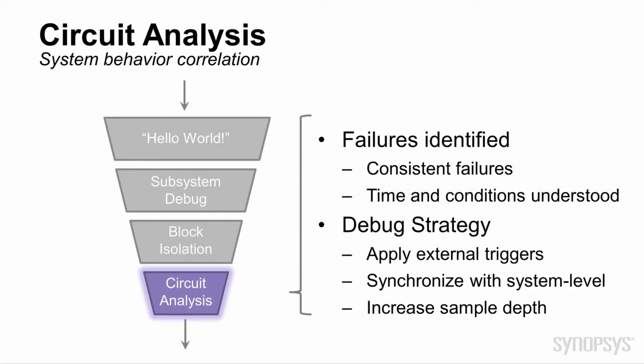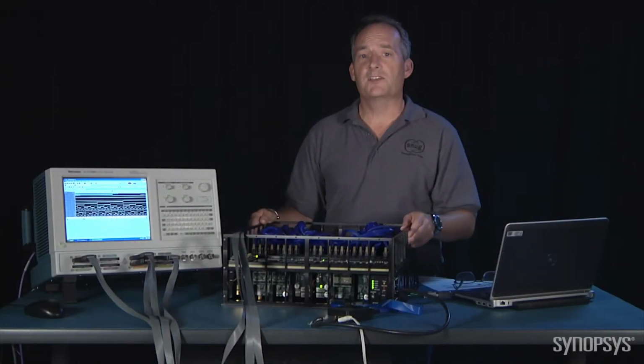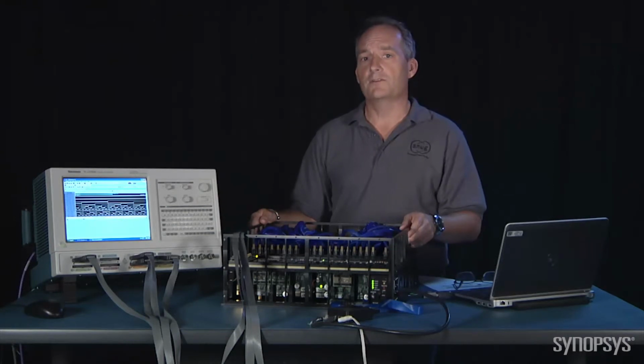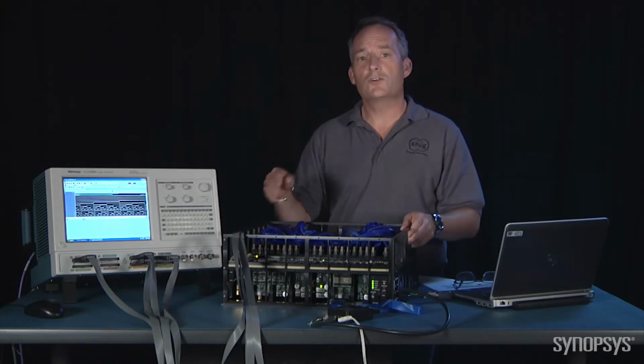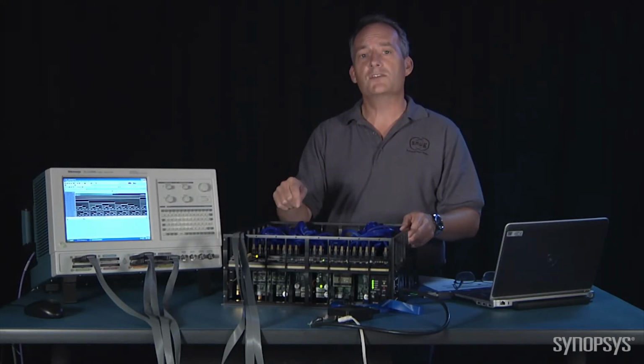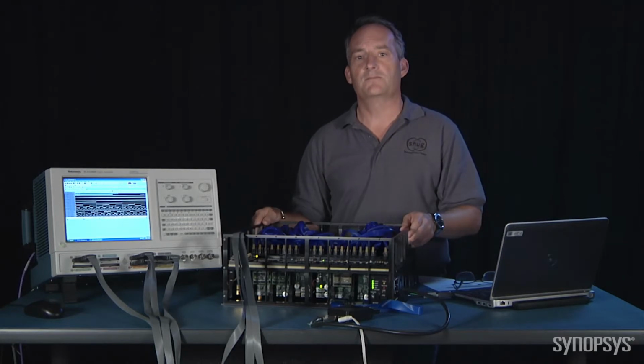During the final debug phase, circuit analysis, we isolate faults further. The debug strategy continues to emphasize high capacity, but also applies this feature to help correlate FPGA-based logic with system-level events. Identify's HAPS real-time debug feature for logic analyzers provides a high-capacity data storage solution which allows you to monitor internal FPGA activity alongside other system-level conditions.